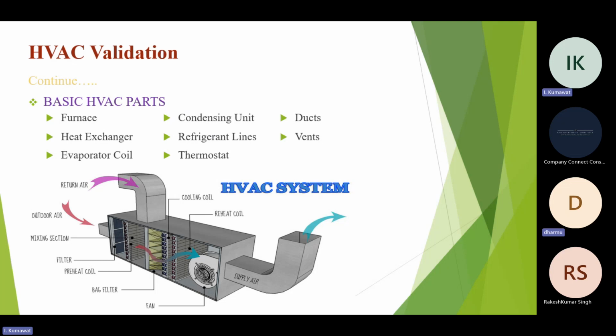So we should have a defined frequency. Sometimes the filter is not working appropriately, or the pressure of the area has increased. Based on that, there are some manometer gauges or units that identify whether a particular filter is working appropriately or not. Based on those observations, we can rethink that filter, whether it is in good condition or not.